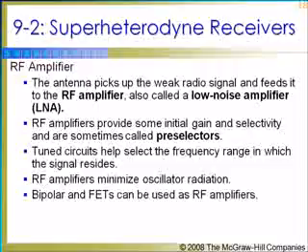In communication receivers that do not use an RF amplifier, the antenna is connected directly to a tuned circuit at the input to the mixer, which provides the desired initial selectivity. This configuration is practical in low-frequency applications where extra gain is simply not needed. RF amplifiers improve sensitivity because of the extra gain, improve selectivity because of the added tuned circuits, and improve the S/N ratio. RF amplifiers minimize oscillator radiation.